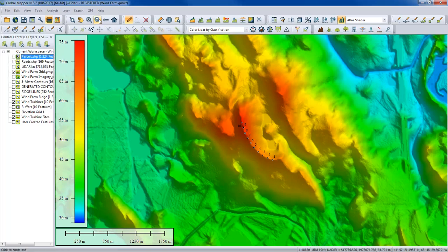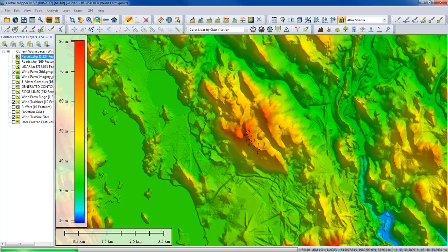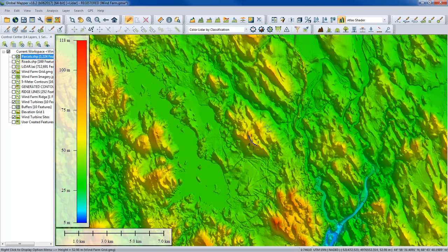And I'm once again going to zoom out just a little bit further than previously. Let's zoom out to the extent of this terrain data. And what we want to measure here is the visual impact of these wind turbines. I'm going to choose one of the wind turbines at random. It doesn't really matter which one, but that's going to become the basis of my viewshed analysis. A viewshed allows us to determine from a given location what can be seen, or the reverse. If we target a specific feature and we can determine the height of that feature, we can see from where